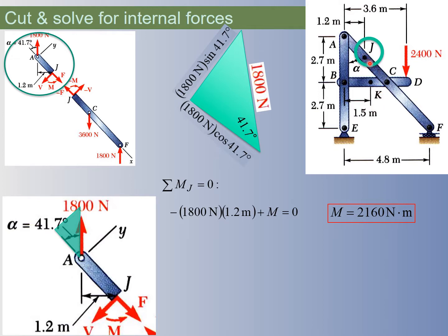So instead of J, if we start walking down this beam and getting farther and farther away from the arm, getting a larger and larger R, that internal moment is going to get larger and larger as we walk down that beam. So don't just solve for one case. Think about what is happening internally at different points.